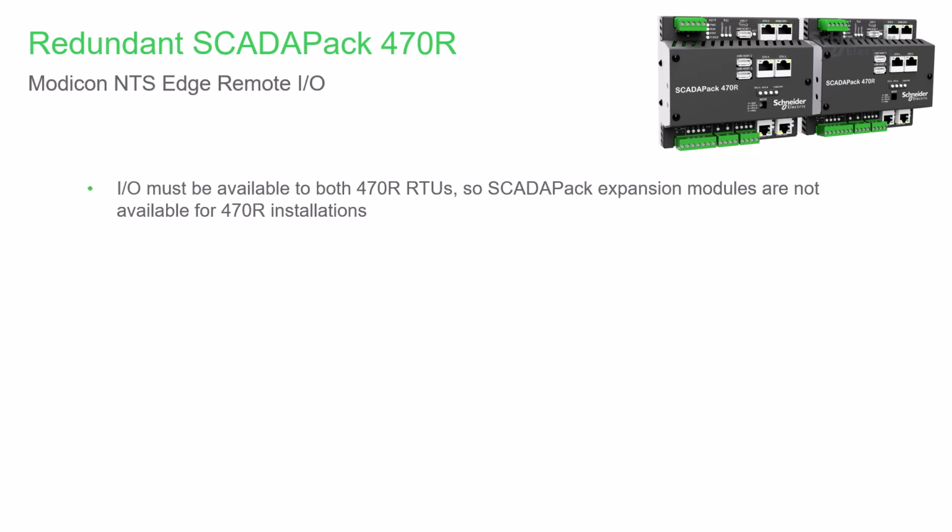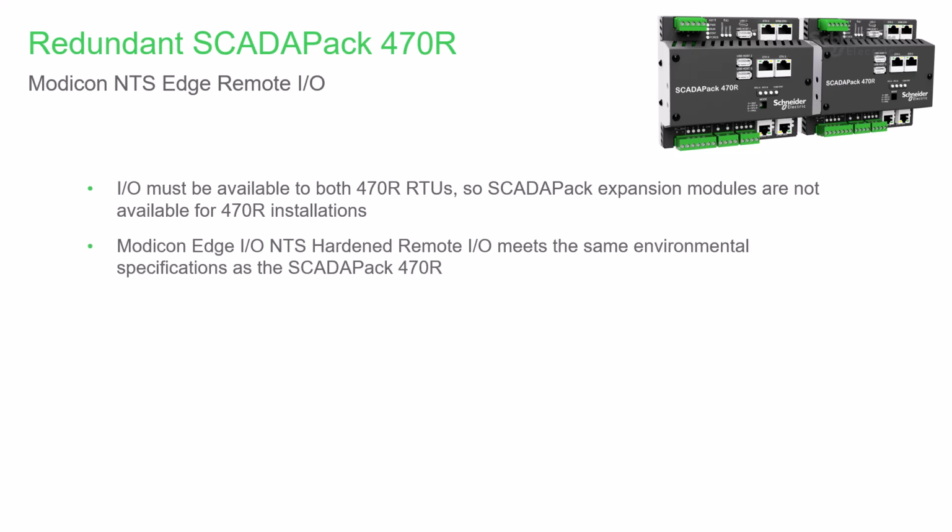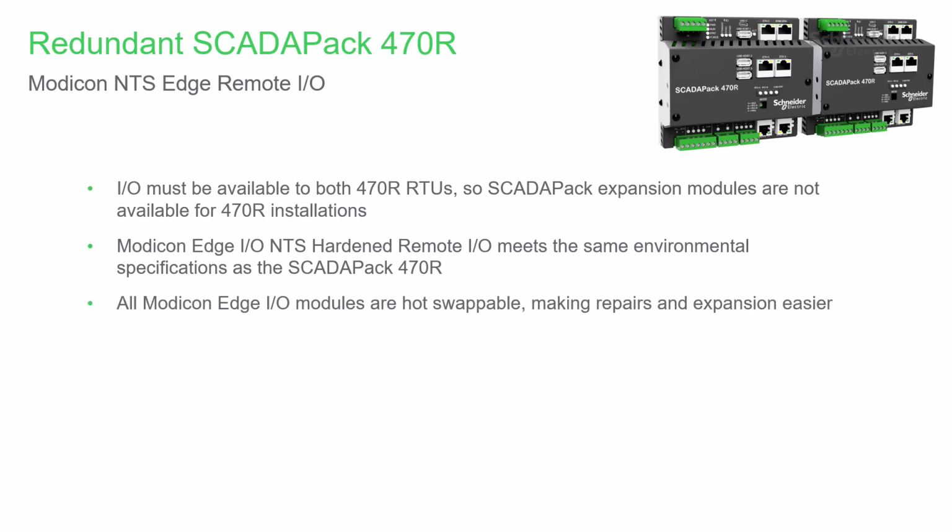Next, let's take a look at the Schneider Electric Modicon Edge Remote I/O. As I/O must be available to both 470R RTUs, SCADAPack expansion modules, which connect to one RTU, are not available for 470R installations. Instead, the Modicon Edge I/O NTS Hardened Remote I/O is recommended. It meets the same environmental specifications as the SCADAPack 470R, and all Modicon Edge I/O modules are hot swappable, making